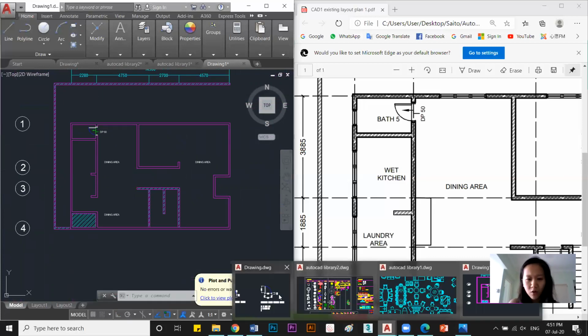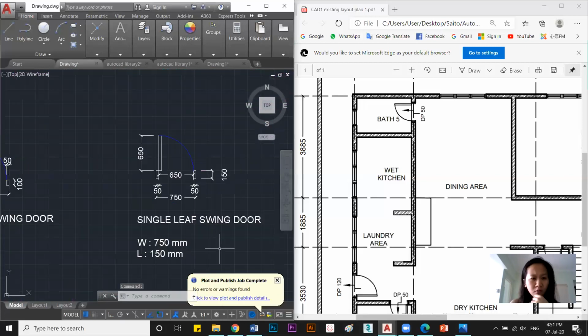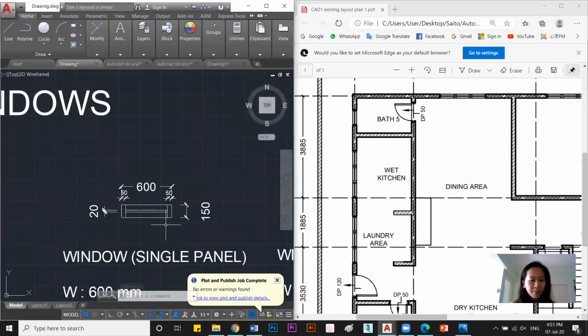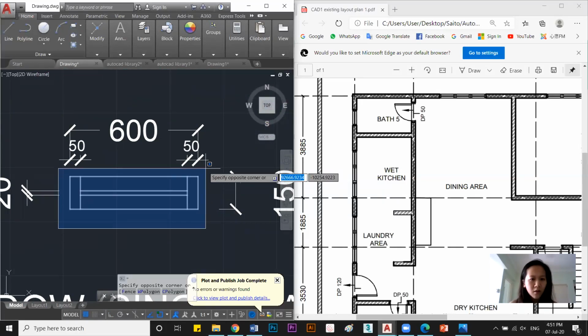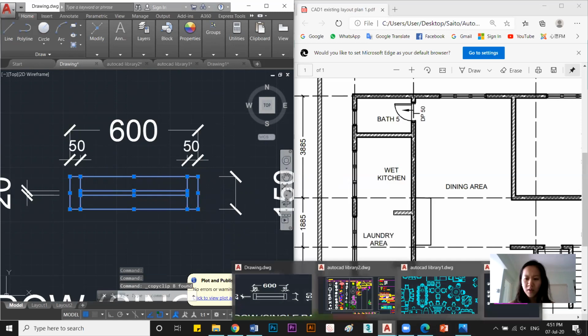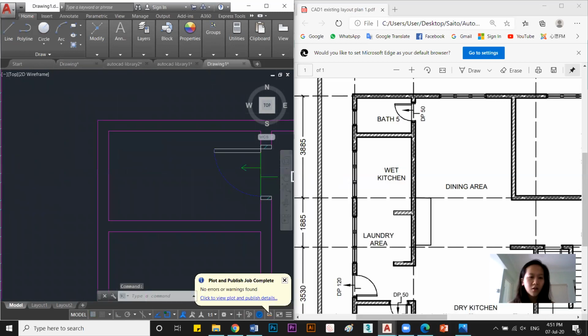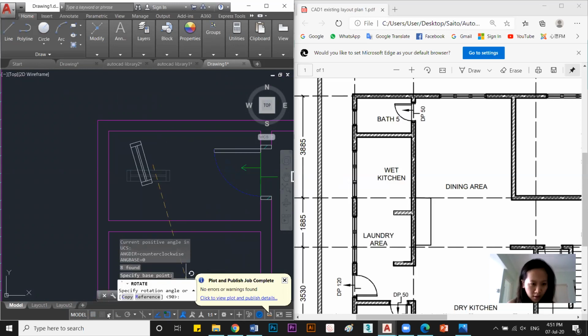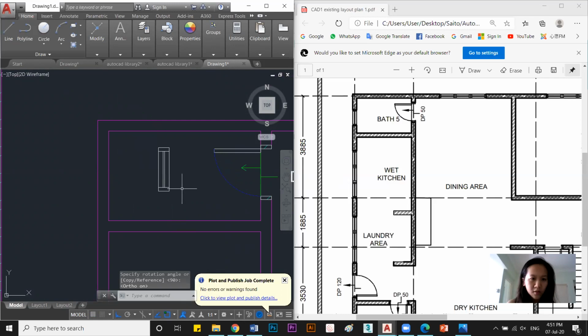So last time you drew a window also, right? Here, you got a window, right? Just copy this, Control C. Go to here, Control V. Then you got the window. Turn on F8. Rotate, move it in. You have the window. All right?